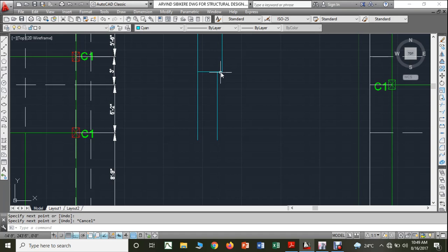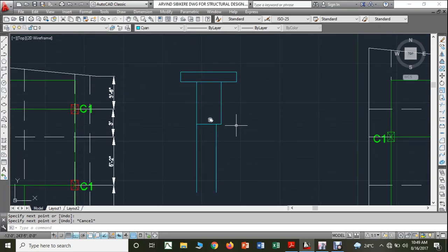Even if it comes inside, it disturbs the architectural appearance. It doesn't look good. It won't give a pleasing appearance. Therefore, usually we keep the beam width equal to the width of the wall. Definitely we won't keep the width less than the width of the wall. We keep it equal to the width of the wall. That is the best option, so that you will have a very pleasant and good architectural appearance inside the building.